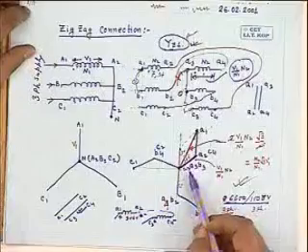However, these voltages are not added algebraically. They are shifted. Voltage available is less. Are you getting it? Therefore, the number of turns needed, in fact, you can easily work it out. What is the number of extra turns one needs in such cases? So that point I wanted to tell. Zigzag is a costly transformer. Of course, it does not suffer from this one.